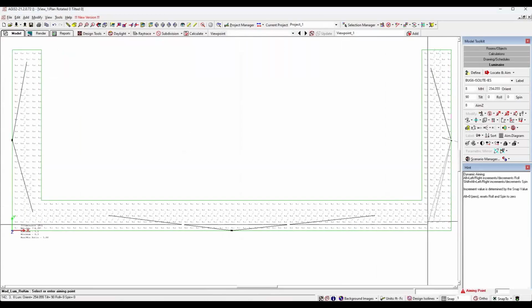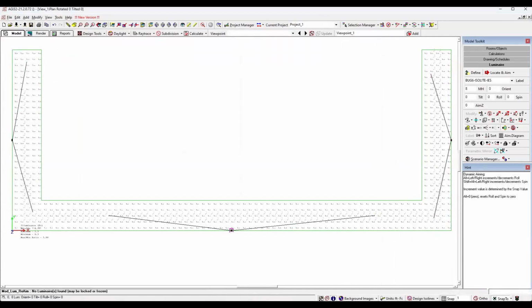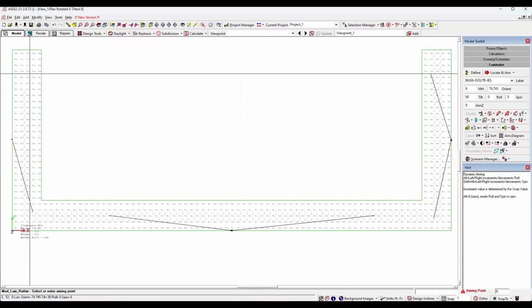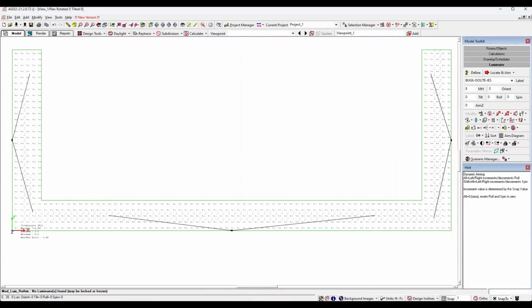So we're going to take each luminaire and we're just going to place it one more time right around where we had it, but this time they are aimed first before being moved. After being moved, we're just going to re-aim everything. Click on it, it'll turn gray. It'll give you an option of where to re-aim it. And we're just going to one more time go ahead and press calculate.